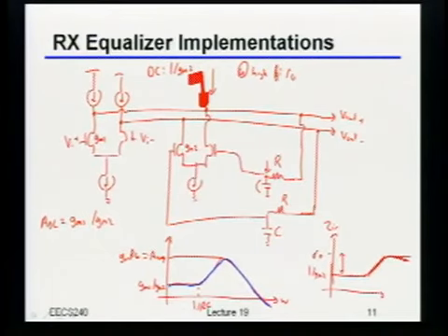Well, hopefully by now you know from my tone that it's clearly not a good equalizer design, or maybe not the best equalizer design. But why is this not necessarily the best equalizer design? Gain. Okay, so what about the gain? It's close to 1, but you need some. Okay, well, the gain is going to be set by that ratio of GMs. That's certainly true. Unfortunately, just about every single equalizer I build, and if you remember I said this before, rather than getting extra gain at high frequency, we're actually going to throw away gain at DC. Unfortunately, most equalizers are going to do that. You're screwing up by putting a resistance in there, right? The noise.